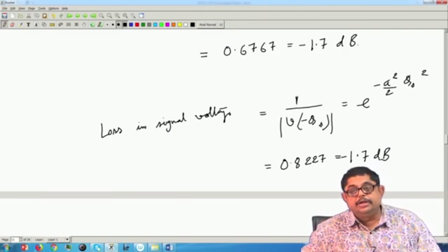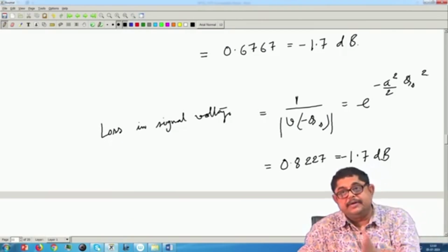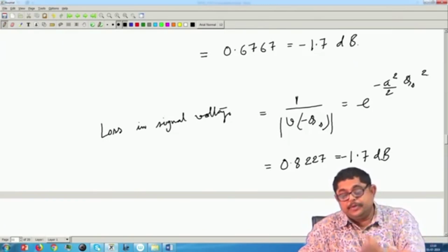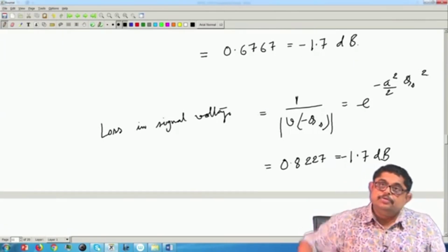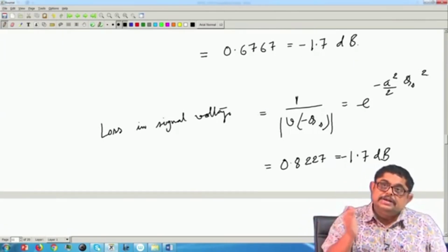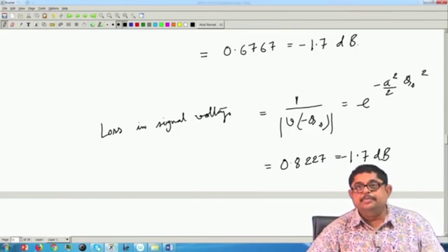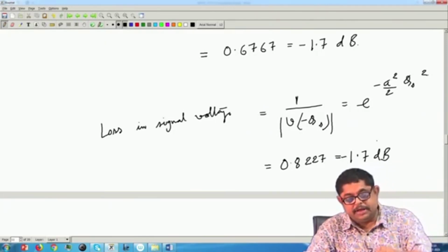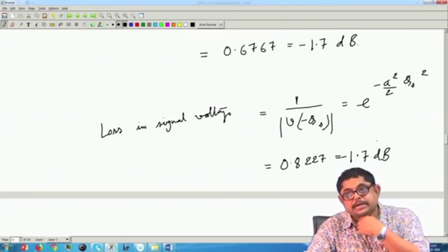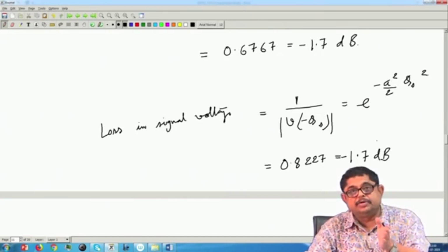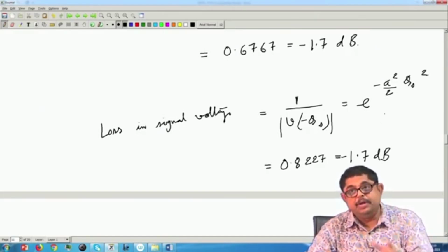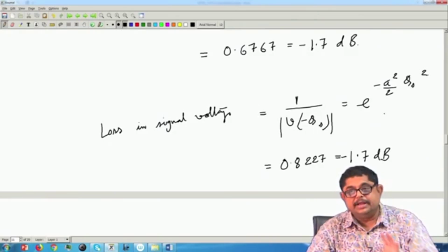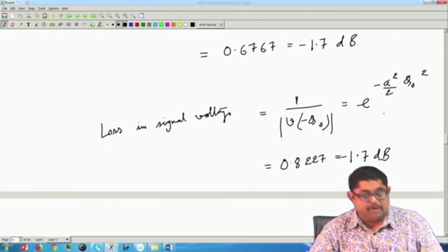So, this shows how much loss you are suffering for squinting the beam, but actually you are gaining in sensitivity, because if you do not have that, your sensitivity will be very poor. So, measurement will be meaningless. That is why we are ready to suffer this voltage loss at crossover, but that shows us that the detection is perfect with a very high sensitivity. So, it is more important to have high sensitivity than encountering some loss.